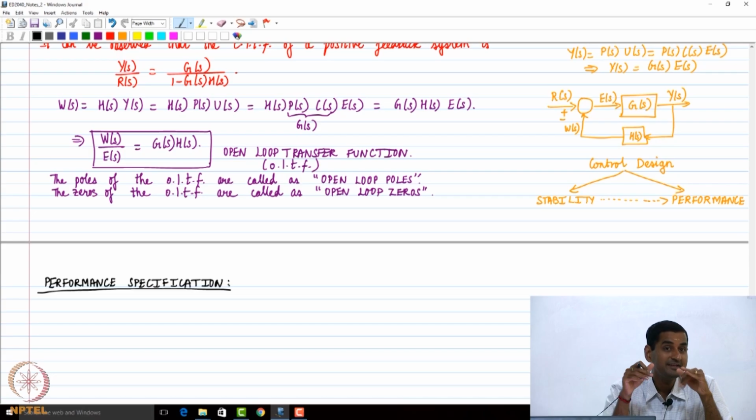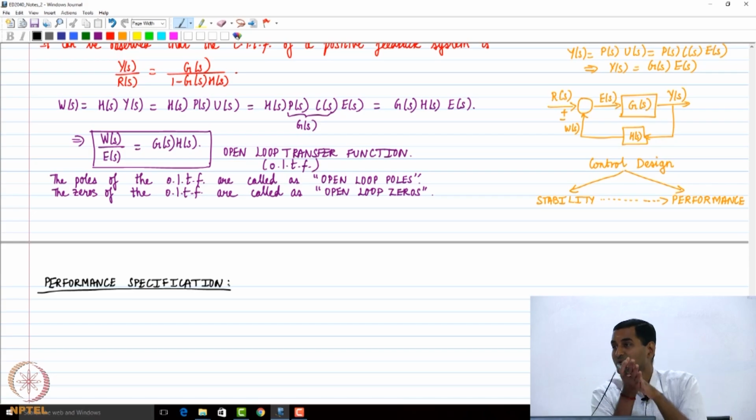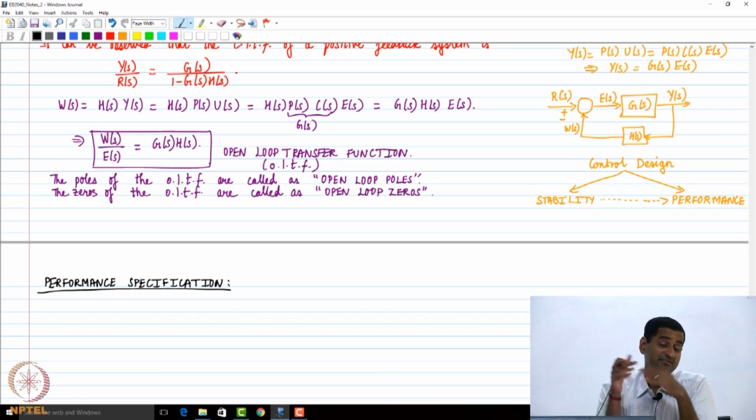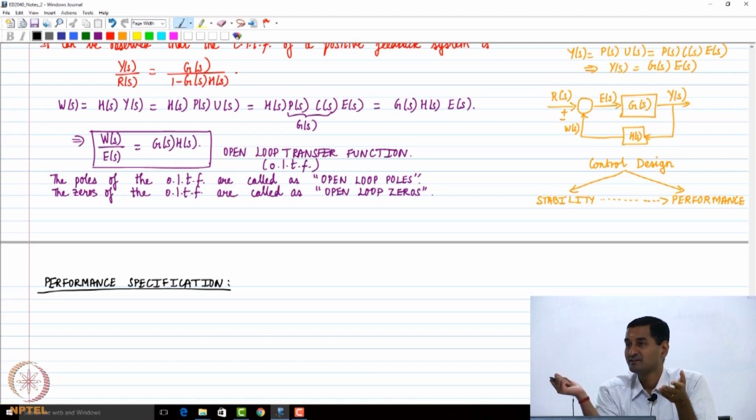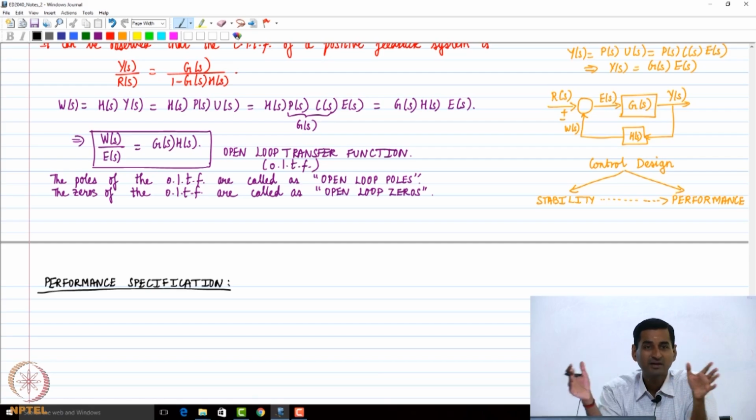Okay, then, how accurately it can maintain it around 25. How fast it can settle around 25 and how close will it remain to 25, right? See, if I have an air conditioner which goes from 38 to 25 in 10 minutes, but then it remains between 23 and 27, I will not be very happy, right? So let's say it cuts off at 23 degrees Celsius and cuts in at 27 degrees Celsius, right? So I will not feel very happy, because I'm going to have a 4 degrees Celsius variation, right?